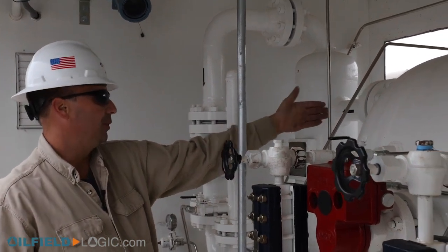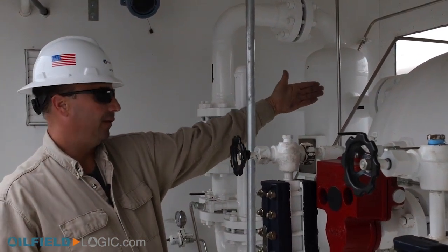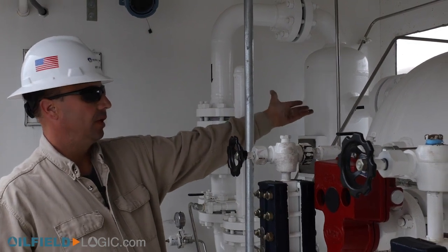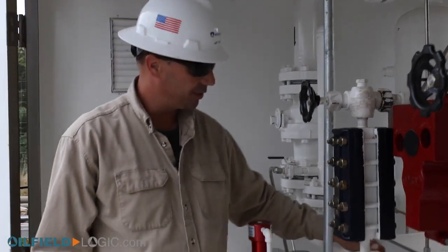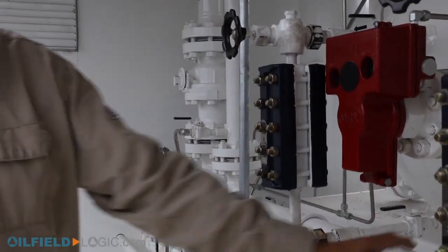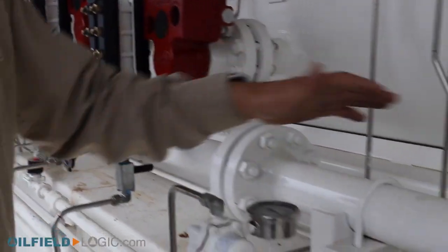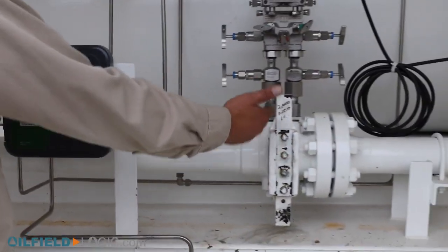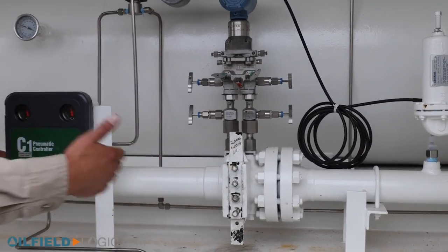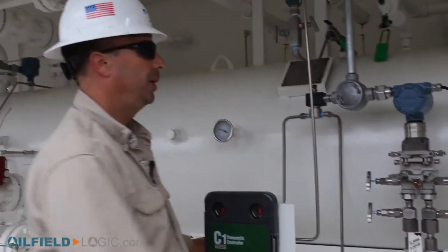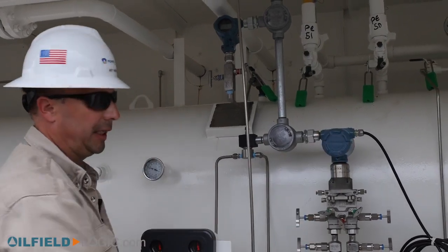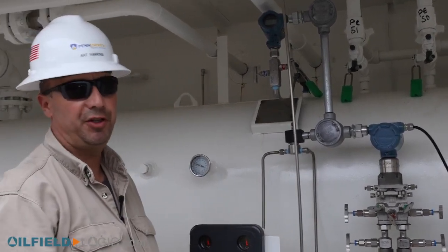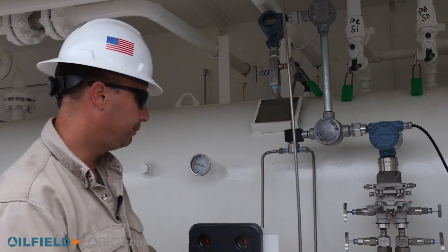Gas being the third and last of the stages of production will be the lightest of the three elements, and that's just going to be on the top part of the vessel and free flow through the flanges and piping to our sales meter. This is our sales meter where we're going to be measuring our gas flow. That's all measured by what we call an orifice meter. There's a plate in here. We'll measure the high side to the low side, and by different calculations and formulas, this transducer will calculate how much production that we're moving through this unit from that one particular well.